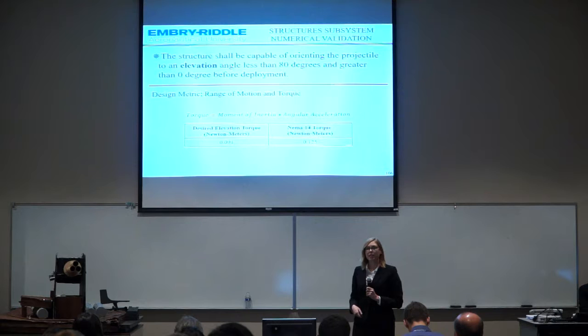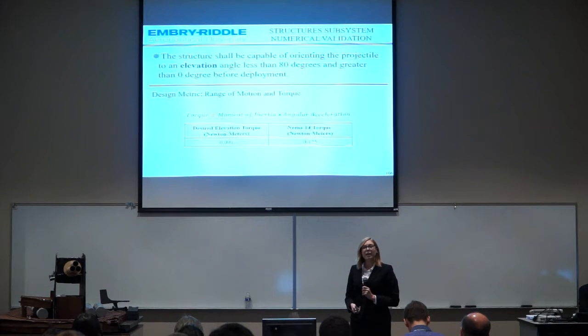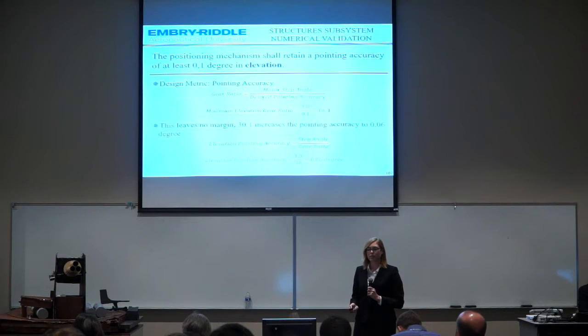Next, the structure shall be capable of orientating the projectile to an elevation angle between 0 and 80 degrees. Our design metric here is range of motion, and torque. There is nothing in the way of our barrels being able to go from 0 to 80 degrees in elevation. The desired torque for elevation is 0.091 newton meters, and our NEMA 14 motors can provide us with 0.125 newton meters.